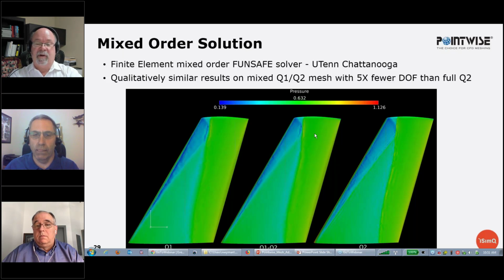Yeah, well, in the cases we've done, we've seen it to be very stable, in fact, and we haven't explored a lot how crudely you can solve each mesh along the way. We've actually solved it fairly tightly, but even doing that, the CPU hit, as you see, was minimal, because you're seeding that next solution with a really good solution from the previous mesh. And because the meshes are self-similar, in particular not only self-similar but perhaps even identical where the boundary layers are and where the geometry is resolved, because that's been specified up front as part of the meshing process, you know those flow gradients.